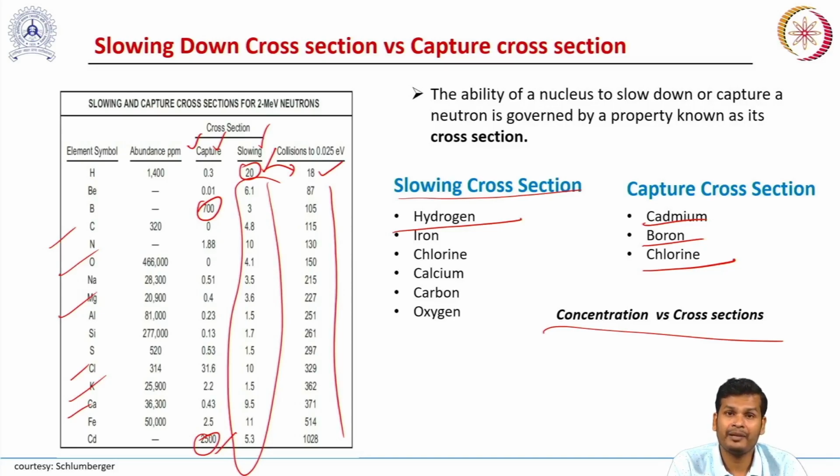So sometimes our neutron logging tool data might be affected by the presence of all these elements even if they are present in trace quantities. That's why, as I have already mentioned many times, we generally record two porosity logs, such as density neutron, density sonic, or neutron sonic, and we never interpret the log without information from other logs. That means all the logs should be taken together to get an interpretation of our well logging data.